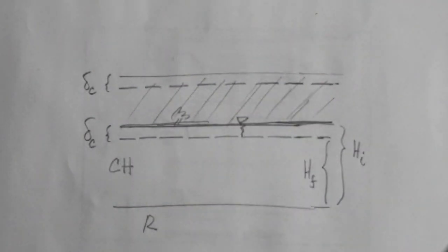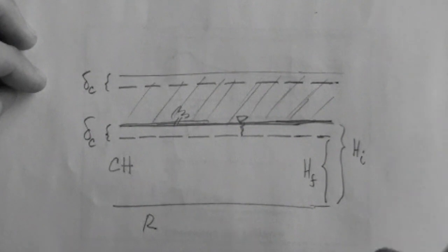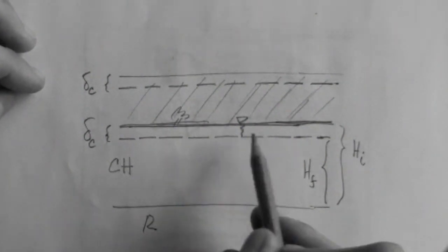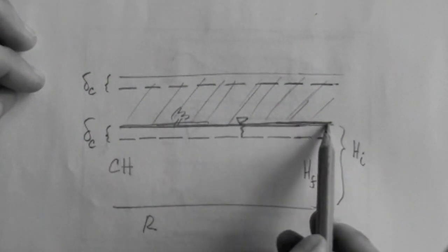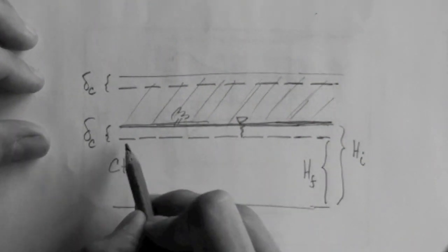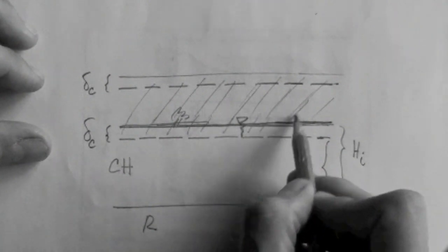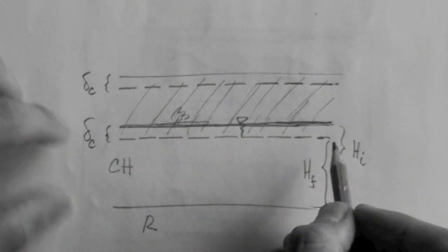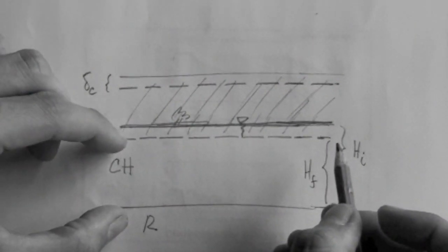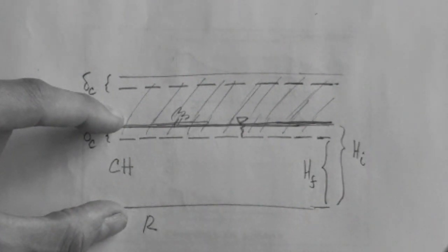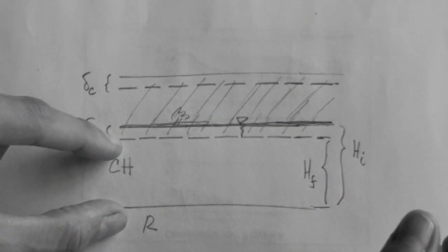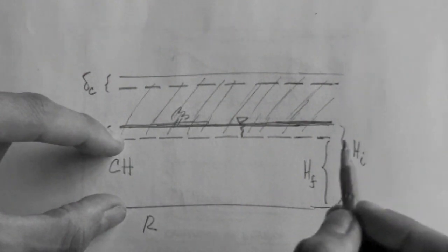If the fill doesn't consolidate itself, this consolidation is essentially the same as this one. Of course, the fill does deform, but we are assuming that the fill is incompressible for this example, because we're trying to understand where the water goes. Well, the water doesn't go anywhere, the water remains there. But relative to the location of the new interface between the fill and the clay layer, remember the clay layer was this thick, and now it's this thick, meaning after consolidation, it becomes thinner.